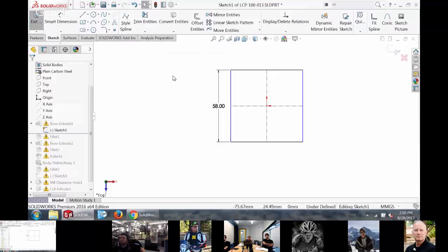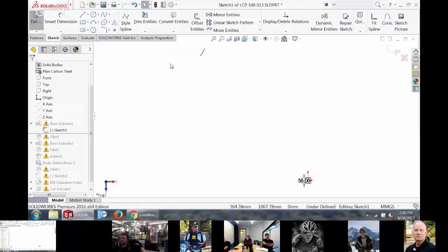One problem is when you're in a sketch and you've evaluated the sketch and you don't see the problem, try hitting F. What is this doing out here? It didn't really see that to flag it like, hey, this is an obvious error. It didn't know whether I wanted the square or the line. So it just told me, hey, you've got one open and one closed contour, but it didn't show me where they were. By hitting that F, I zoom out to fit the sketch onto my whole screen. Then I can see problems I might not have seen before.